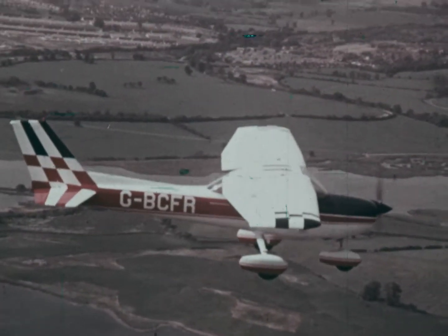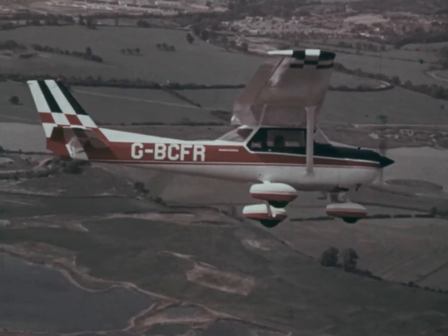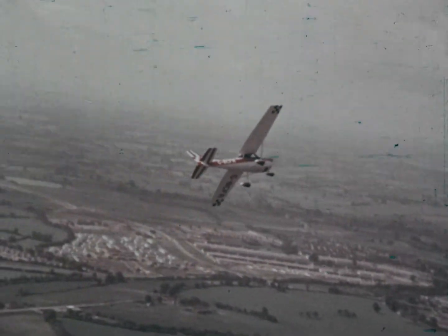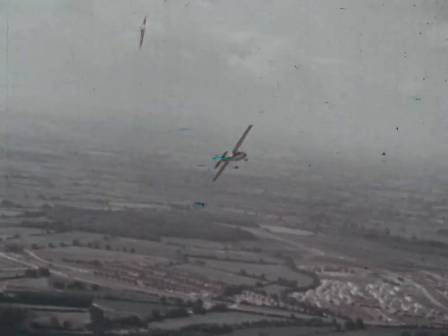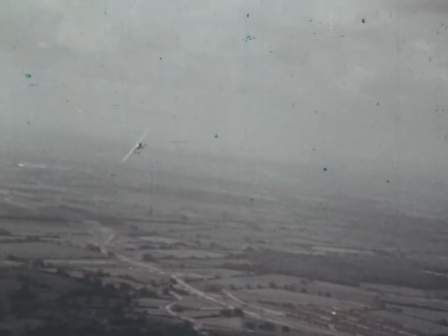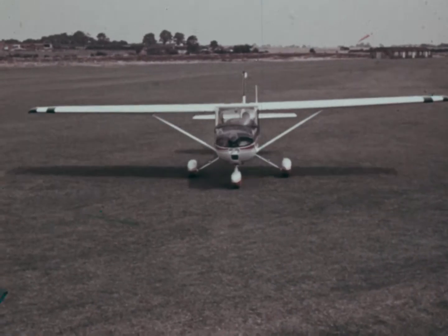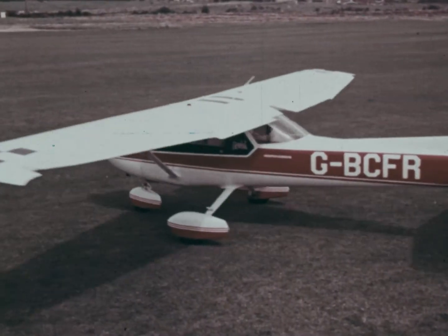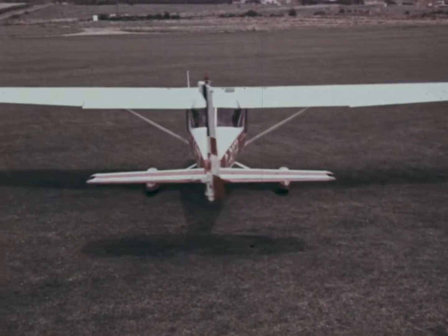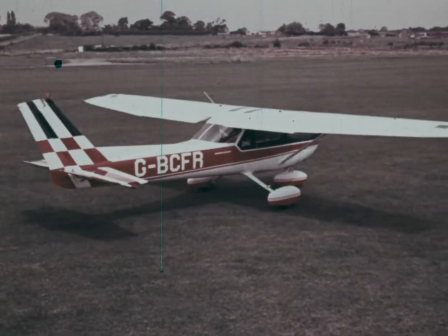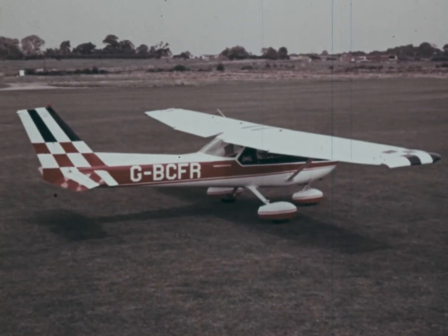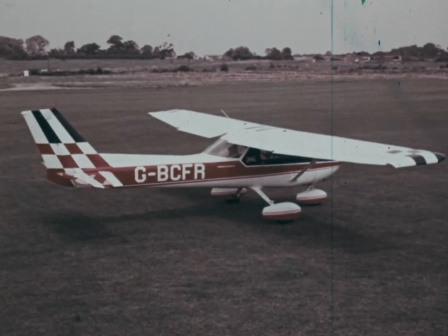The controls of an airplane enable us to maneuver it accurately and safely under all normal conditions of flight. Control is achieved by moving hinged surfaces on the trailing edges of the tail and the wingtips. The elevator attached to the tailplane, the rudder to the fin, and the ailerons to the wingtips, all of them operated by controls in the cabin.